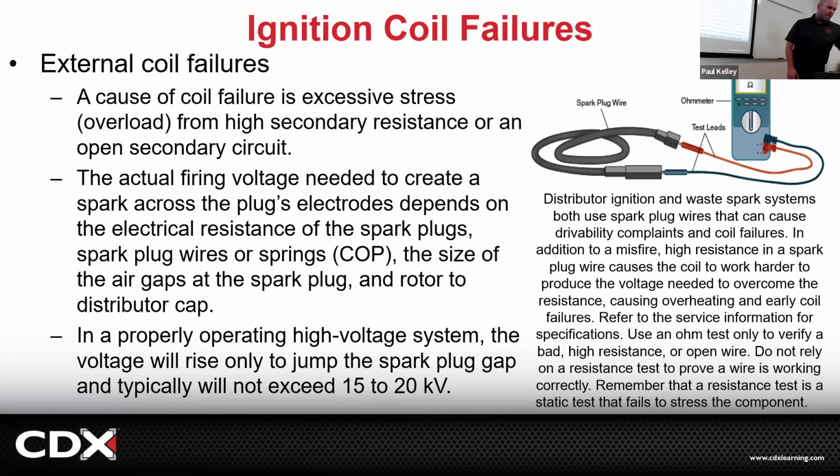Your coil has to work harder when there's more secondary resistance. Think of secondary resistance on the meter. You could be like, hey, it might have 4,000 ohms. But how many ohms would it be if it's a full-on open? OL, which our typical meters measure up to millions of ohms. If it measures up to millions and it's out of the limit of the millions, that means it's billions, whatever the number. It's a lot. Mucho, mucho, macho. Right? That's even harder on the coil.